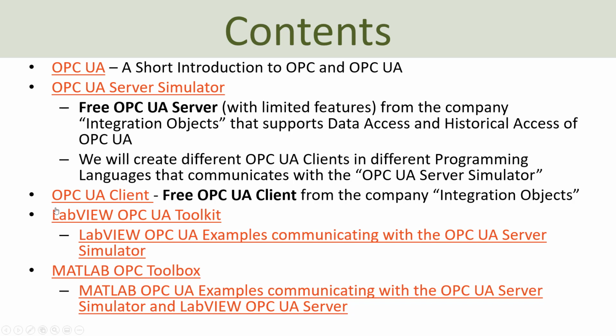The same company also has a free OPC UA client which we can use in order to test the OPC UA server. So we will also use this OPC UA client. Then we will use in LabVIEW something called the LabVIEW OPC UA Toolkit. This is an additional package to LabVIEW. LabVIEW is a graphical software created by NI, and this LabVIEW OPC UA Toolkit is also created by NI, so it's an additional package you need to buy in order to use the OPC UA feature within LabVIEW. So here I will provide some examples using this LabVIEW OPC UA Toolkit and then communicate with this OPC UA Server Simulator.